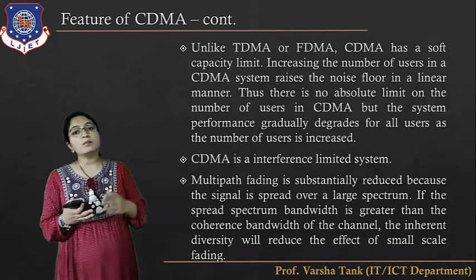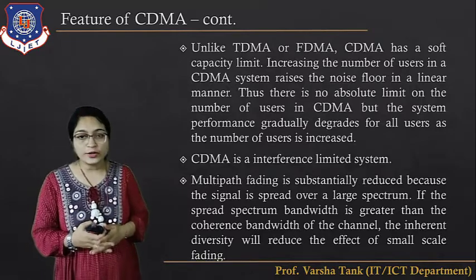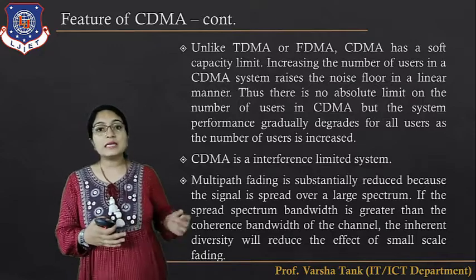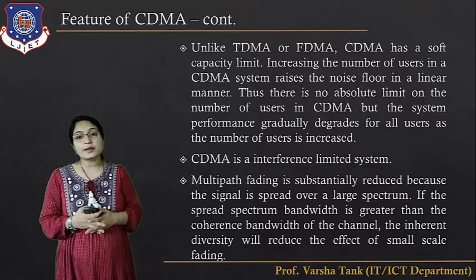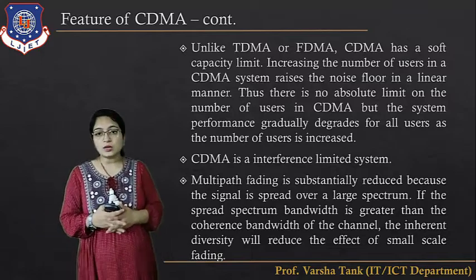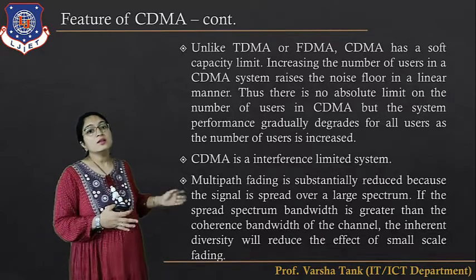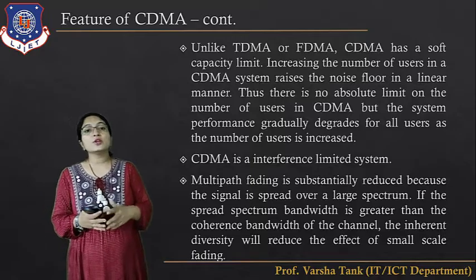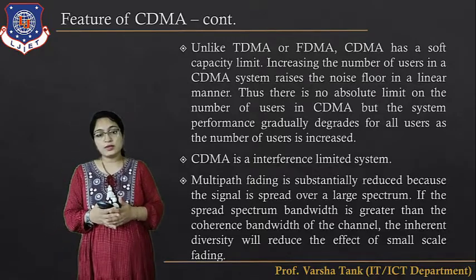Then the next feature is that multipath fading is substantially reduced because the signal is spread over a large spectrum. That's why. If the spread spectrum bandwidth is greater than the coherence bandwidth of the channel, the inherent diversity will reduce the effect of small scale fading.